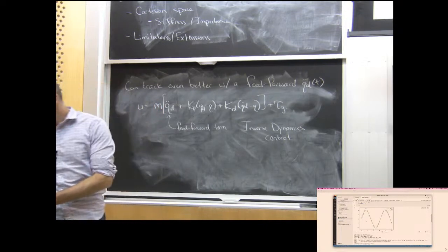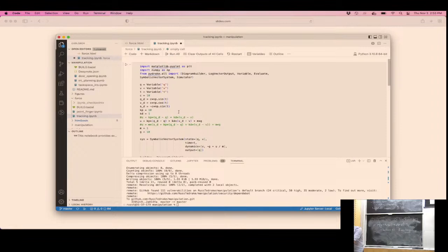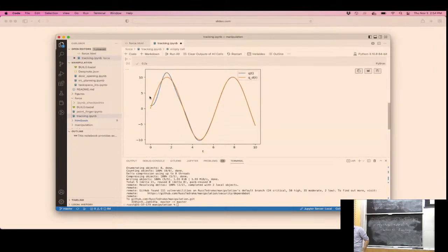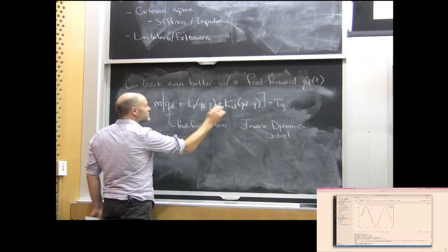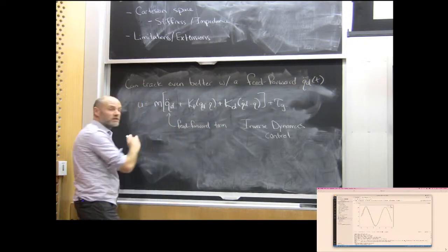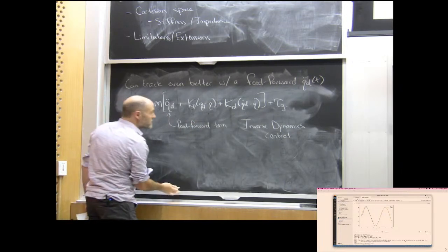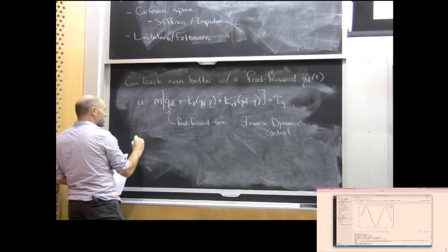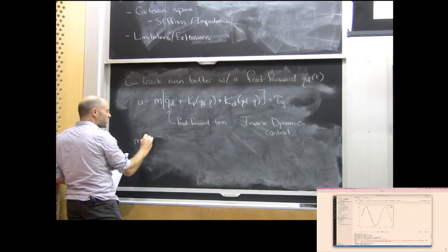And of course, I will try to convince you here that if I were to put the feed forward term in, things get even better, that I get beautiful convergence to the nominal trajectory, and I'll stay on the nominal trajectory. I won't deviate on every oscillation. Once I'm there, I'll stay on there. It's actually easy to see that, okay? The reason to do this and have mass multiply, I'm going to scale my Kp and Kd also by the mass, is because then if I write out the closed loop dynamics, I can say that I have mq double dot